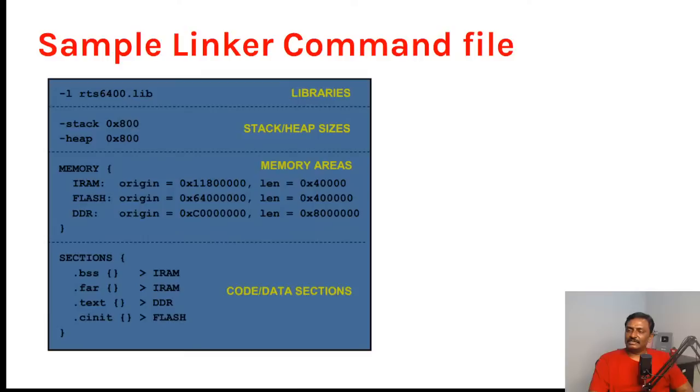Architecture for commercial use? Okay, ARM core is widely used. If you go with the majority of manufacturers and the majority of the market, the most widely used is ARM architecture, like Cortex-M4. But ARM is a company that sells only the silicon IP. They don't manufacture the chips. They sell it to the manufacturers. Like Texas Instruments purchases this IP and manufactures the Cortex-M4 ICs. And you have ARM cores on NXP. There are different manufacturers.